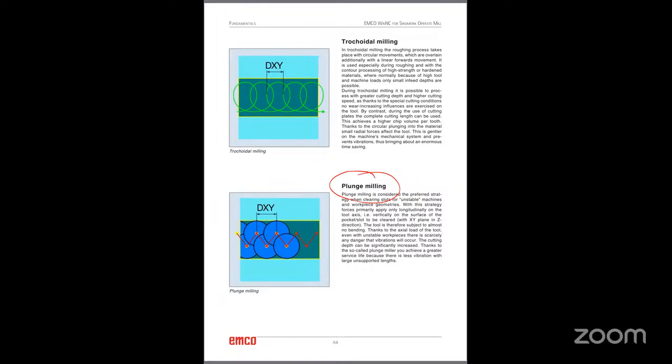We will get more cutting depth. Tool life will be more. So this strategy will be used in deep pockets, slots, thin walls, weak fixtures, long tools, large unsupported length, etc. So these are the advanced strategies that we will use in different CAM software such as Mastercam, Siemens, etc.